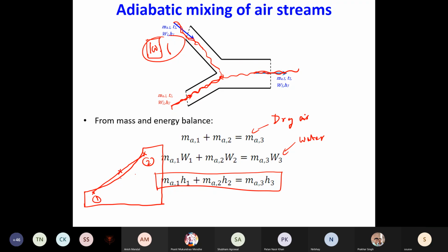And if you draw it on the psychrometry chart, it can go beyond your saturation line. So what does that mean is, you simply check the temperature. Draw a vertical line. Your exiting state cannot have relative humidity more than 100%. So your exit state would be this, with this much amount of water condensing in your mixing box itself.